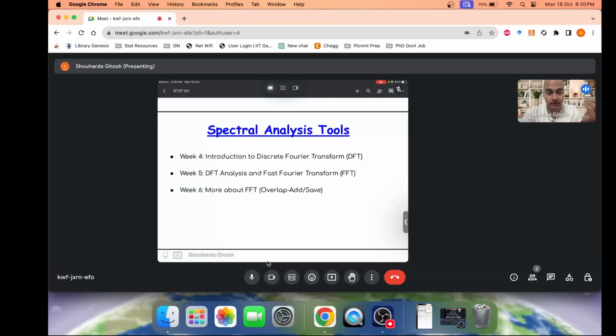So can you store the frequency response of these discrete time filters in a computer? Again, no. So what do we do? The frequency domain is also sampled, discretized into frequency points. So now you have discrete in time and discrete in frequency. This is the scenario, and that's where the discrete Fourier transform comes into the picture.